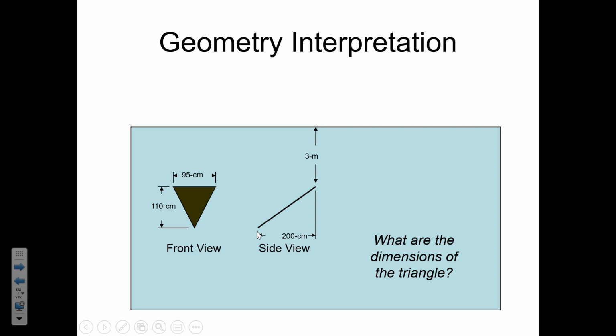And so let me just put something up here on the whiteboard to illustrate. We've got the physical inclined triangular gate, and its vertical projection is 110 centimeters, and then the projection of its width, this dimension along the bottom, is 200 centimeters.